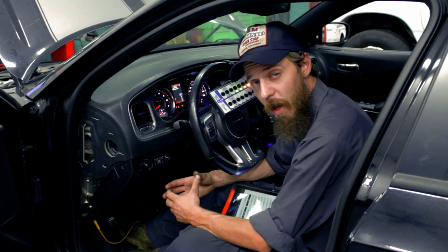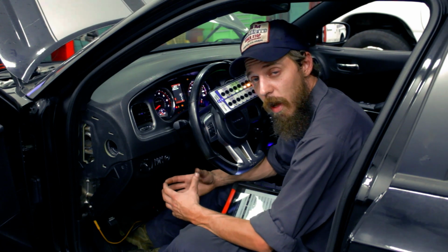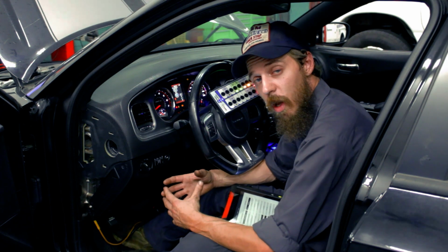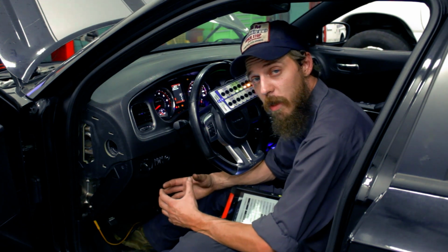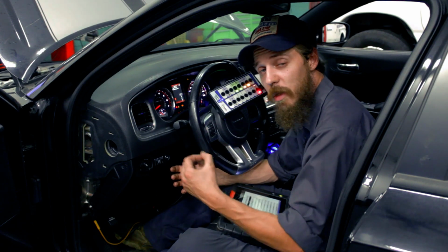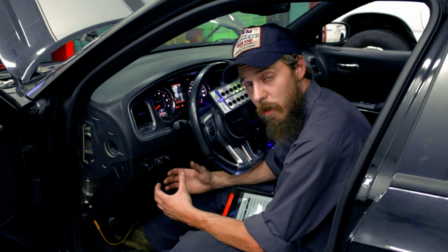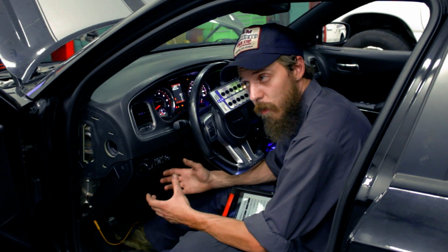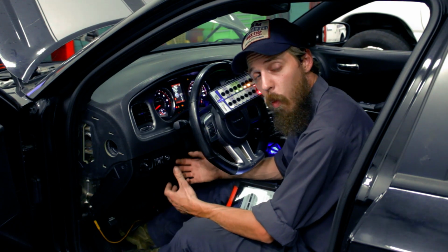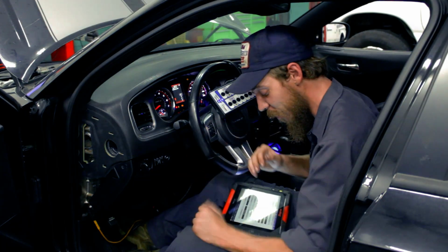In reverse or drive, we should see actual transmission temperature. In park or neutral, with that high system voltage, our transmission temperature will actually be a substituted value, which is gathered from the PCM and the engine coolant temperature sensor reading. So it's an interesting little bit of data, and we're going to delve into why we care about that. But this is take 2 of this particular section.